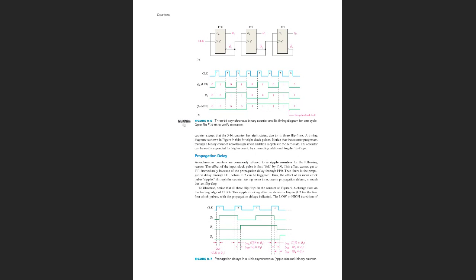For the second flip-flop, FF1, the clock is connected to the output not Q0, and for flip-flop 2, the clock is connected to the previous not Q1. So by analogy, the same history, and this is why this counter is able to count from 0 0 0 to 1 1 1, from 0 to 7.